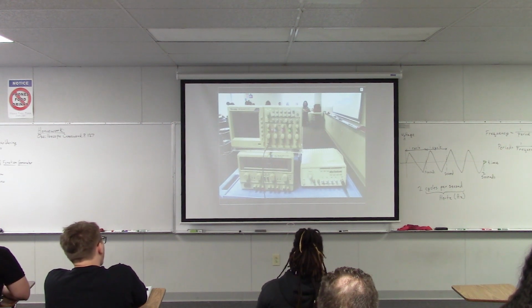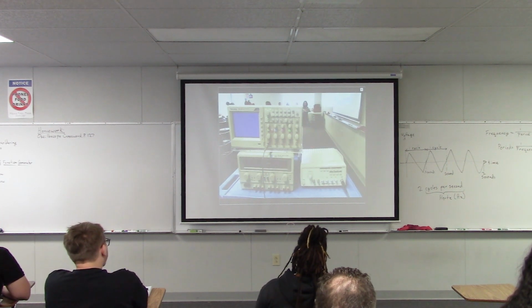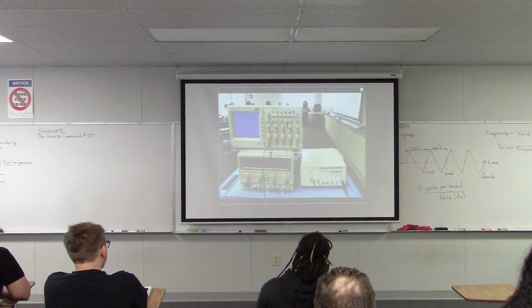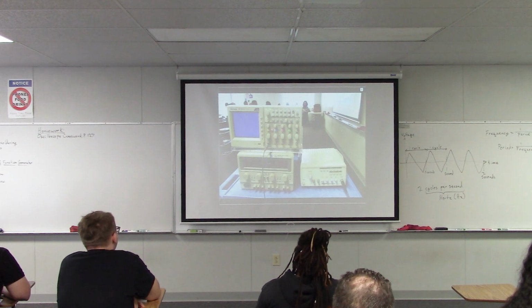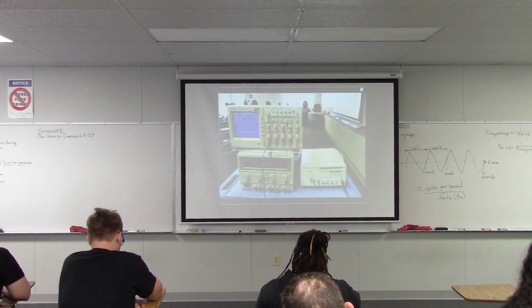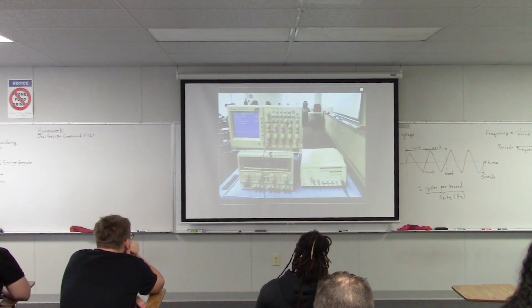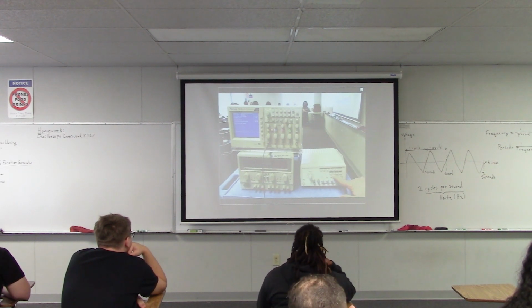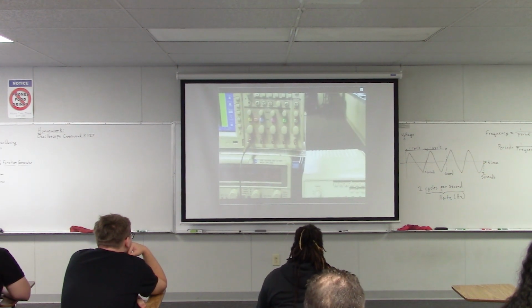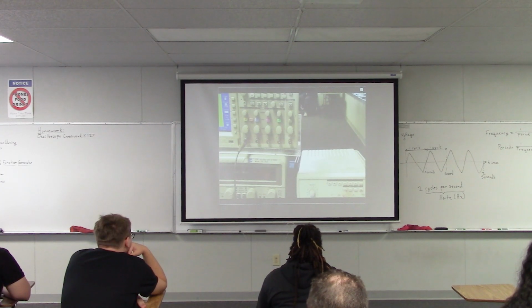All right. So let's talk about the controls for the function generator first. So we said that we could control three main things about the signal. What was the first thing that we could control about the signal? The shape, exactly. So if you look down here on the function generator, we have buttons that have different shapes on them. We've got this button, which is for square wave, the middle one is for triangle, and the one on the right is for sine wave.